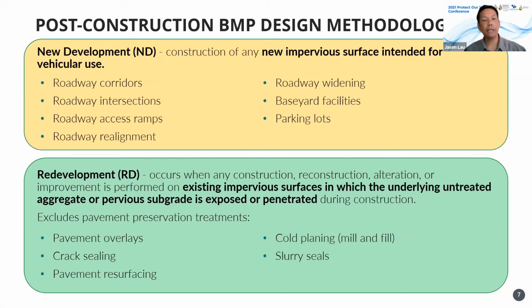And redevelopment is any activity that occurs on existing impervious surfaces in which the underlying treatment, aggregate, or pervious subgrade is exposed or penetrated. So it follows basically the same definition as disturbance that Jon provided earlier. So it does not include pavement preservation treatments such as overlays, cold planing, and resurfacing.